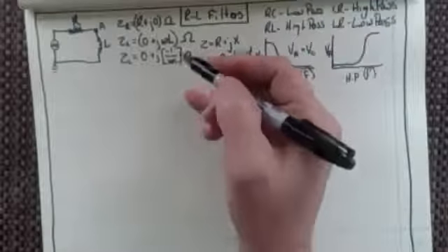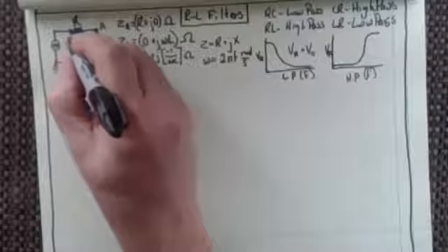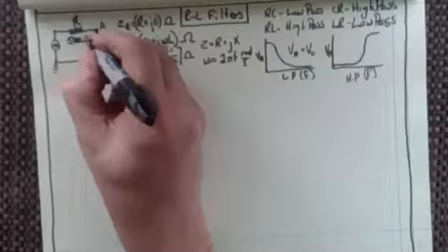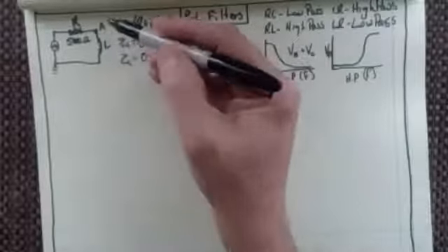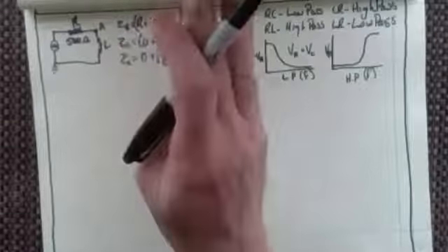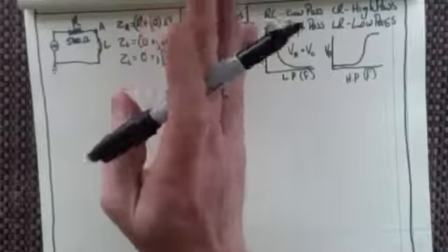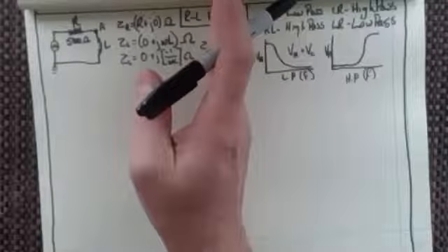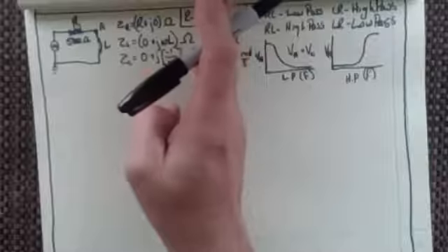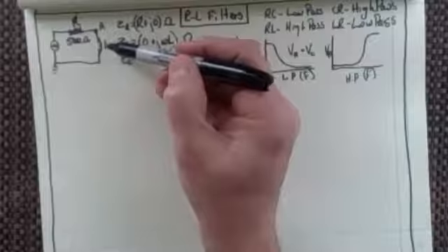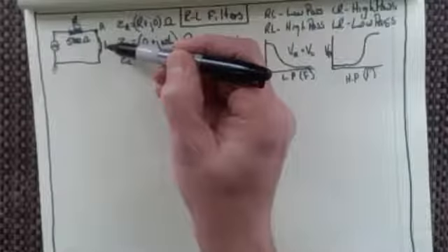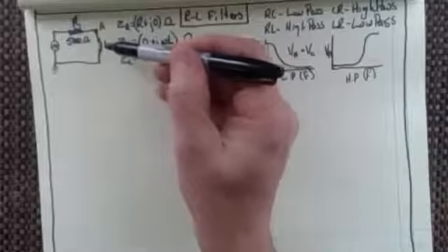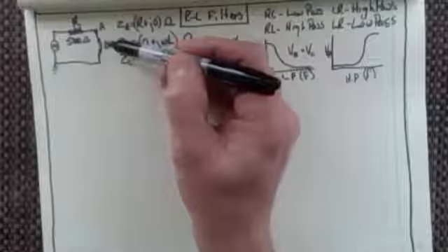Now let's get back to this and let's look at what I've got. Originally I said that that was 5,000 ohms, right? And so we wanted to look at how L would compare there in 3 different instances: a very low frequency, a resonant frequency where the real resistance of the resistor equals the imaginary impedance, or I should say the reactance of the inductor, right? So that's what we want to look at. That's the second thing. So let's look at these.